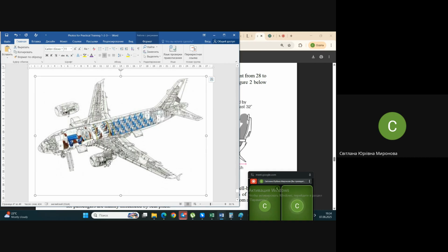So a higher bypass ratio, on one hand, will of course result in increasing diameter, but depending on the aerodynamical perfection of the fan itself and of the inner ducts, it does not quite directly depend on the size of the inner engine. Whatsoever, a turbofan is wider in diameter. Now let's see what it may result in.